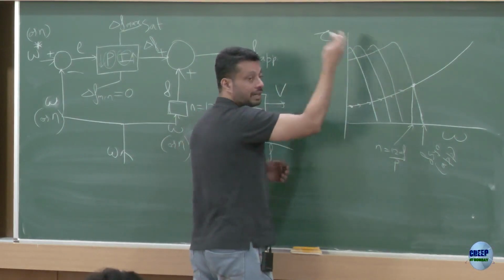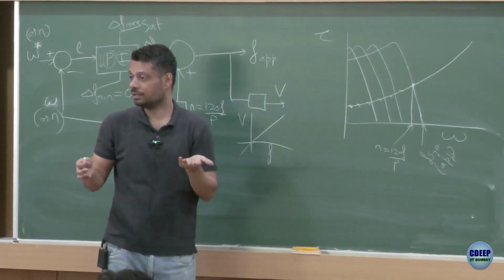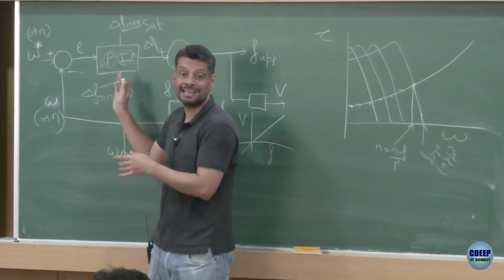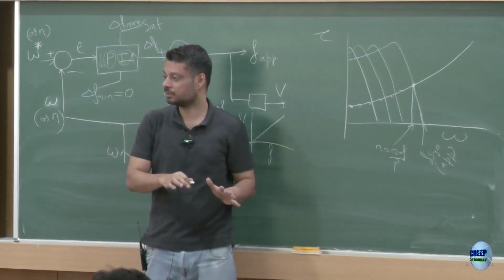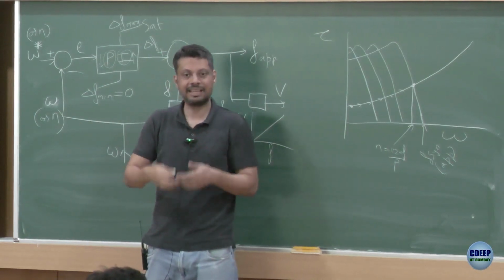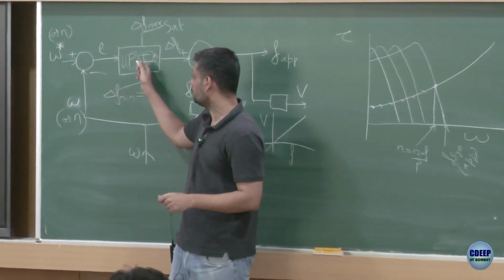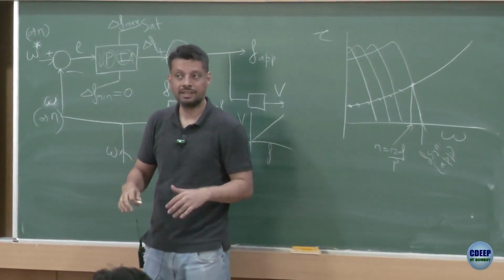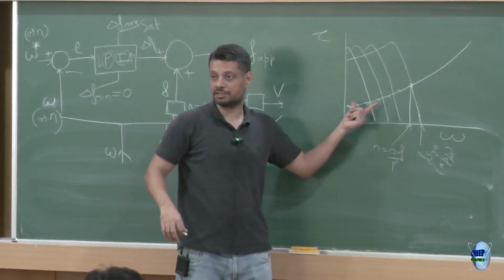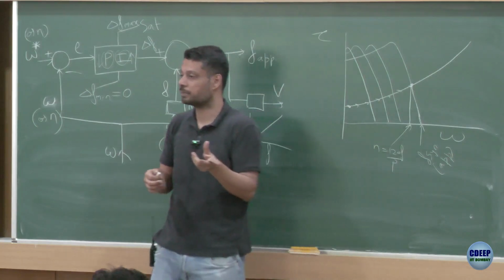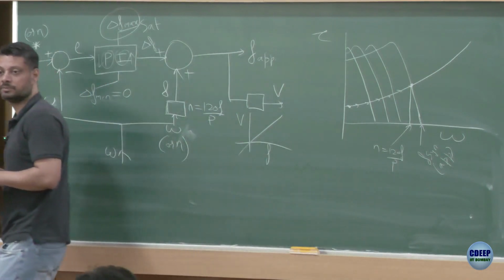And if that is the case, you understand the inrush current will be large, your initial torque has come down, all sort of problems, right. So you don't want this guy to be really fast, you want this guy to be of the same order of response as that of the inertia of the motor, because the motor is a slow system, right, it takes its time to start and rotate. So therefore, to make it slow, one is of course you would choose the values of Kp and Ki appropriately. The other thing is you put a limit on delta F max so that you are never really far away from the point of operation. You would always be just a little bit ahead of the point of operation, and how much ahead you can control by setting this delta F max, right?